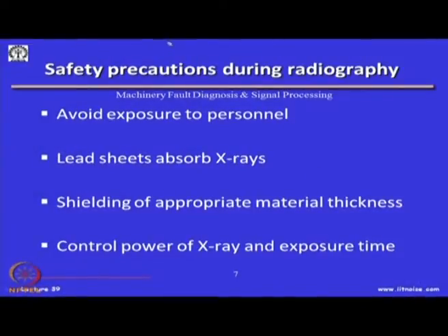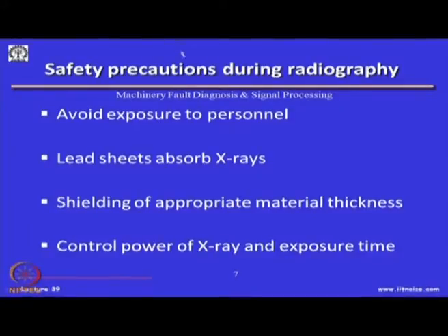So, there are some safety precautions which we have to take during radiography. On top of it, if there is gamma ray radiography or gamma ray testing, we have to be more careful about the nuclear radioactivity associated with such gamma rays. However, in radiography, because as I was telling you, X-rays cannot be seen, heard, or smelled, we have to be careful that the exposure to personnel is avoided.